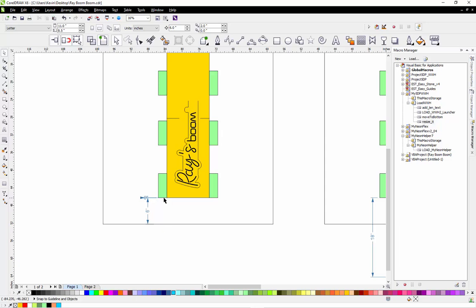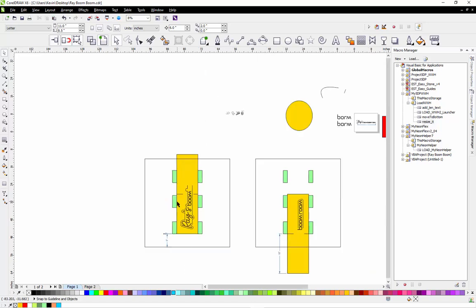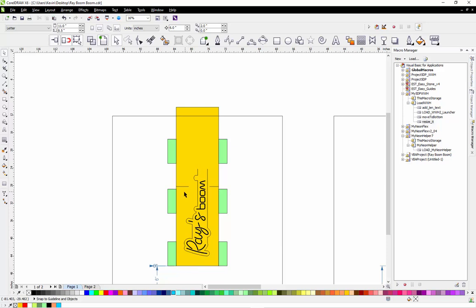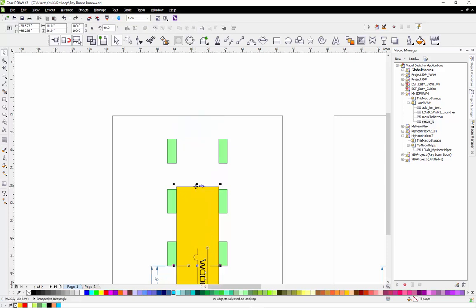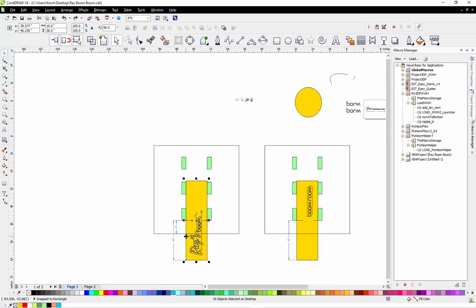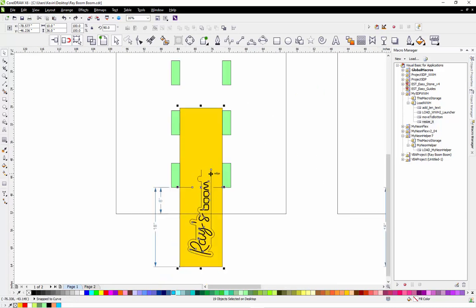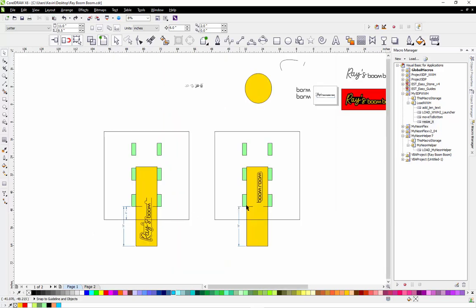So that's why I have these blocks here, because when I slide my stock down, I'm going to slide it right to the edge of that block. So on my stock, I have a line drawn at 18 inches, okay? So once this first section cuts out, I'm going to slide it down to that 18-inch line, and then we're going to do the second part of the design, okay?